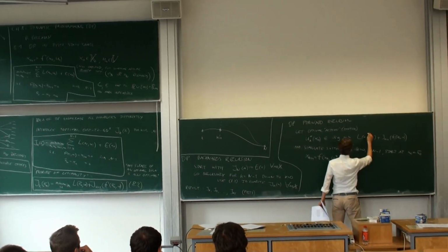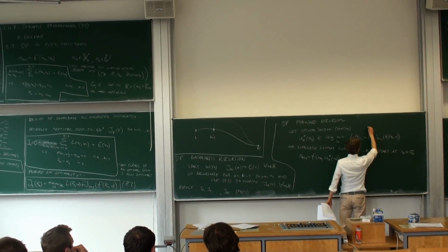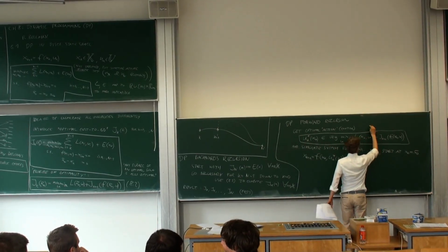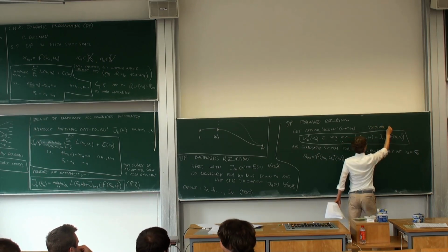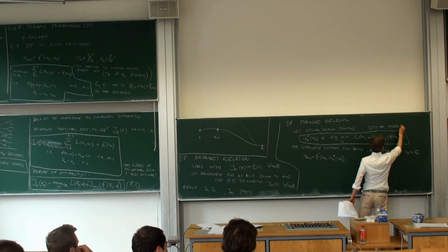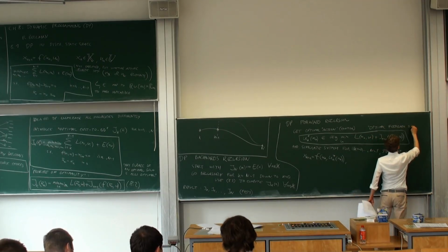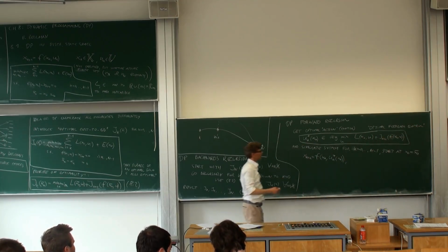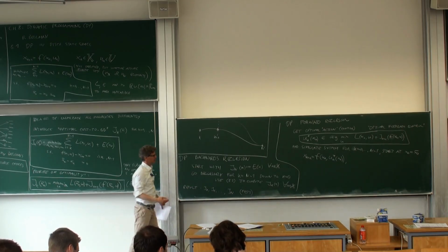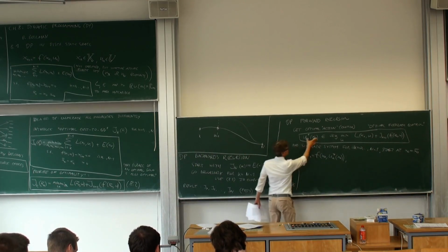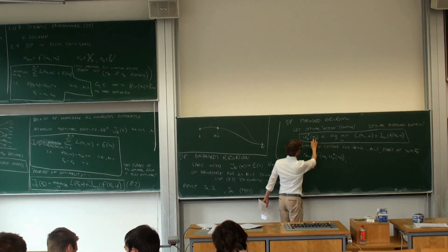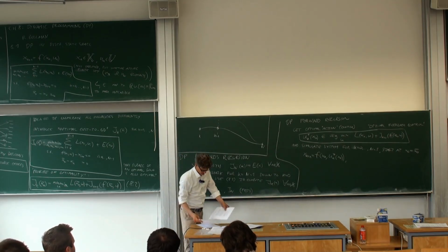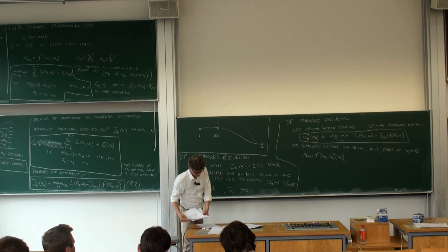And maybe I should call this whole thing, this definition that we have here, the optimal feedback control. Why do I say feedback? Because it's actually very much like a feedback. When we would have a different state, we would get a different control here. So it's not just some value. It's actually a law, because for any x, it would give us a different control. So this is now the forward sweep. And together, this is a way to solve the optimization problem.